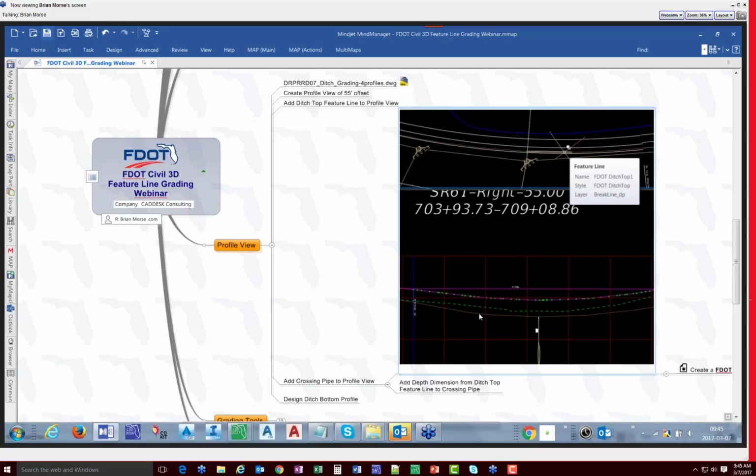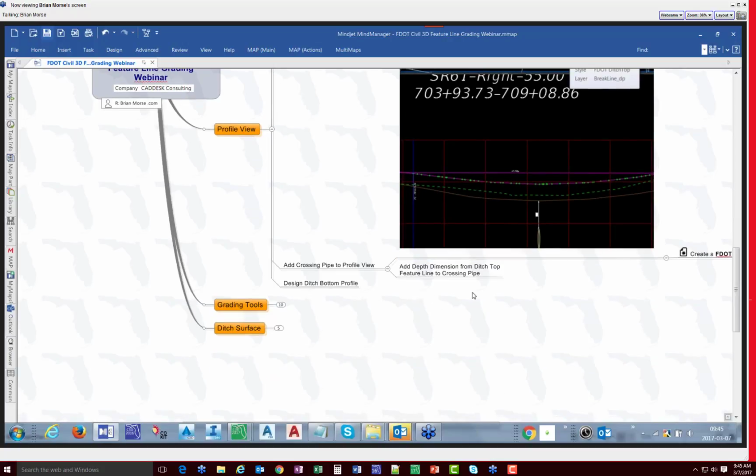Another thing that I didn't show you, which I'm going to skip over for now, is you could make an AutoCAD dimension for use in just a profile view and just change the vertical exaggeration on that. So you could apply a scale factor to that, and that way you could use just regular AutoCAD dimensions for this kind of labeling, because maybe you like the format better and you don't have to fiddle around with the other style that wasn't formatted to the way we like to see the output.